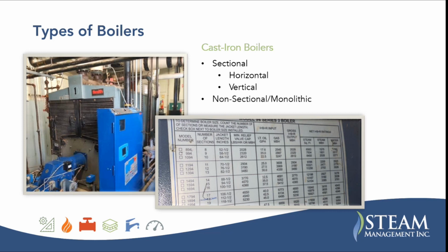One of the things that boilers sometimes don't do well at partial loads is maintain their combustion efficiency. Your air to fuel ratios can get off a little bit, but with modern controls, that's really been tightened up a lot. As for a condensing boiler, I don't know. I would think it would operate the same, but I'm not sure about that. That's a good question. Thanks, Cody.